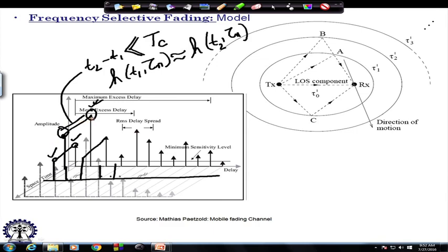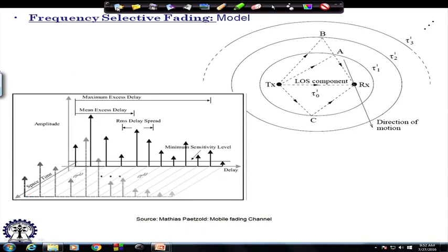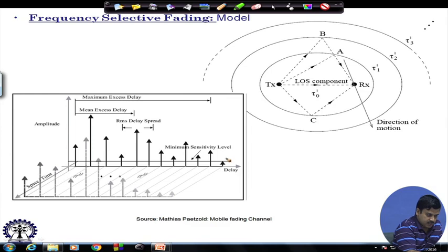So, if there was a continuous measurement, we would get fluctuations, and if the variability is very fast, this is the kind of picture. If the variability is slow, the channel is going to fluctuate slowly. So, this we have to clearly understand. If we understand this, we have understood one of the most important things of this multipath propagation in time and delay axis. Okay.